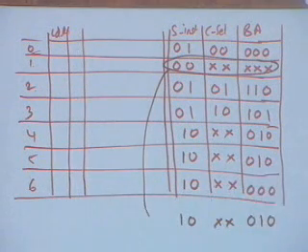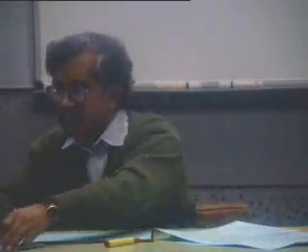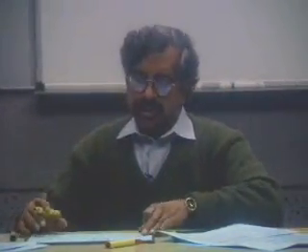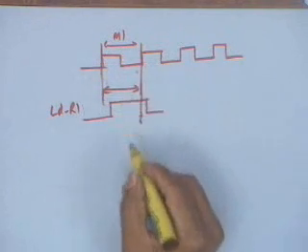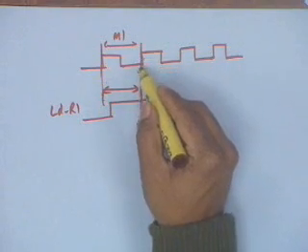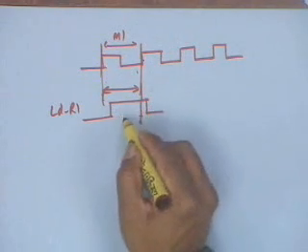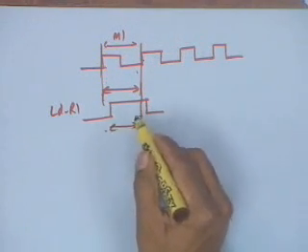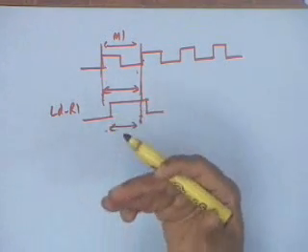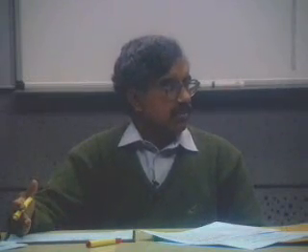Let me first answer the other question that was regarding the timing. The timing that we had discussed was that all my load operations, all my state transitions, are at the trailing edge. If you consider this to be a clock period, it happens at the end of the clock. And all this time is available for all the combinational delays through the multiplexers, the subtractors, the comparators. If you follow this model consistently, all your operations will work.